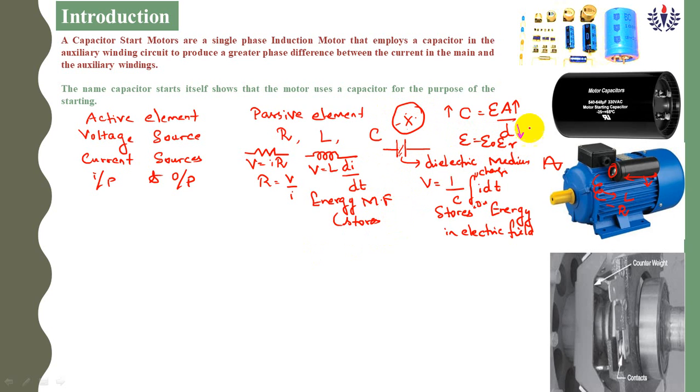What type of capacitor? It is the AC type capacitor. In the market, if we ask for motor capacitors, they will give this capacitor, we just insert it. Capacitors are of different types: parallel plate capacitors and electrolytic capacitors are available in the market. In our AC machine we are using the AC capacitor.